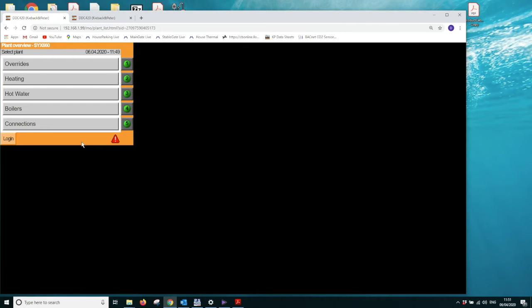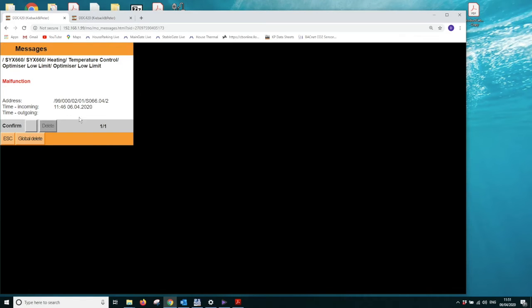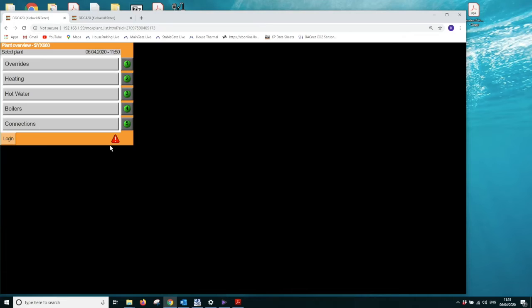And so if we look at the alarm, it comes up with some information that says SYX 660 heating temperature control, Optimiser low limit, and Optimiser low limit. So it's not exactly the most clearly explained reason for the alarm, but that's why we're doing this video. You can confirm the alarm when you've logged in at user level 2, but you cannot delete it because at this moment in time the alarm is still active. So the message is still current, but now it's stopped flashing because you're taking responsibility of it.